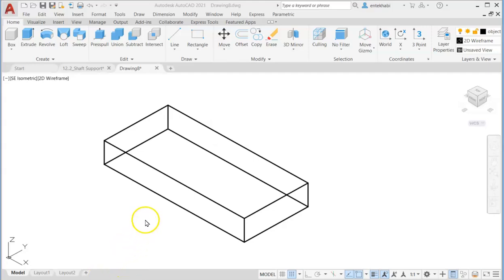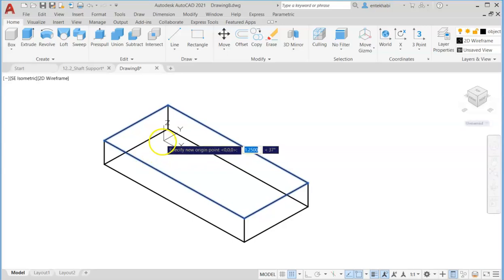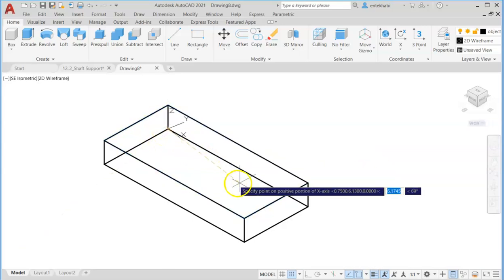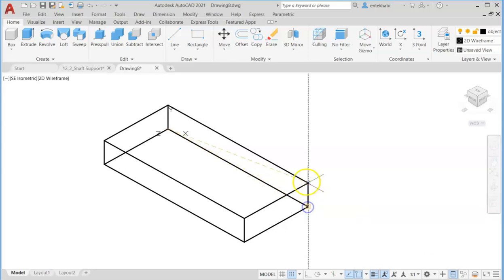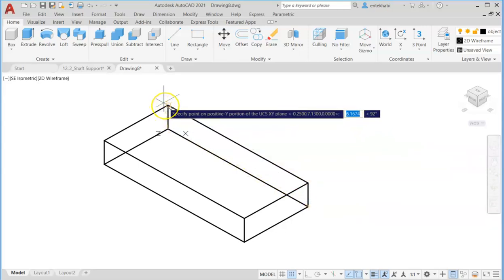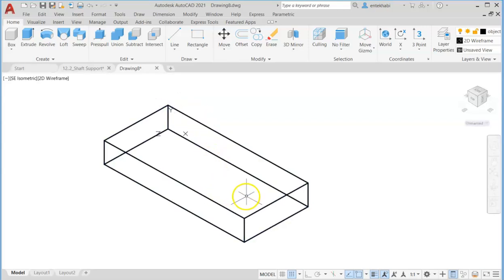Okay, now we are going to change our UCS 3 points. Selecting the 3 points option, we pick the origin to be on this corner here. And x-axis would be other corner with selecting endpoint. And selecting another endpoint for y-axis. We select those points where XY switches parallel to the screen.